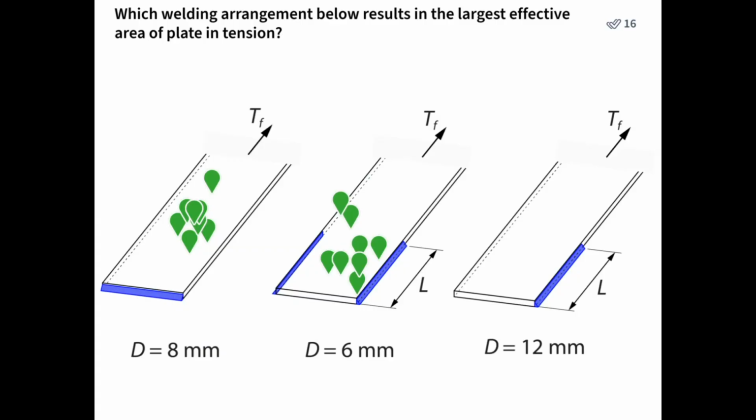And so in cases like this where we have this transverse weld, a load that's perpendicular to the applied force along the width of the plate, all of that area is going to be effective in tension. Now usually we don't just do that. We might also have some other welds here because it's not the best practice to just do that kind of thing. Sometimes we might look at a situation like this, and it's actually pretty common to have two longitudinal welds because it's more ductile, it stretches more before they fail, and it's usually easier to do that kind of weld.